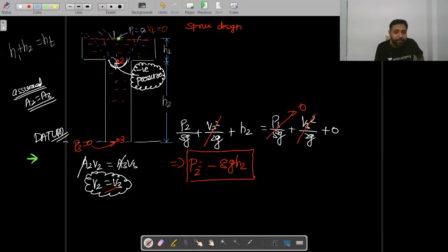This air may dissolve into this molten metal, and later on it can reach the mold cavity. Once the casting is solidified and that dissolved air was trying to come out, let us say it didn't come out, so that air will be entrapped. And if air is entrapped into the casting, that will lead to several gaseous defects, like blowholes, blisters, and pinhole porosities. This is what we call the aspiration effect.